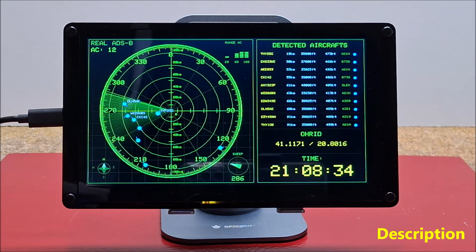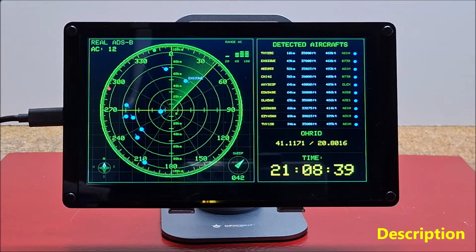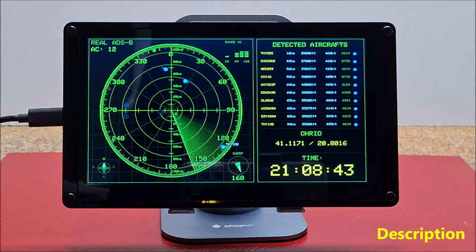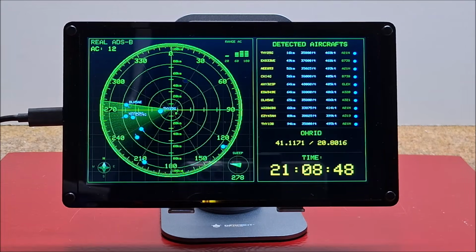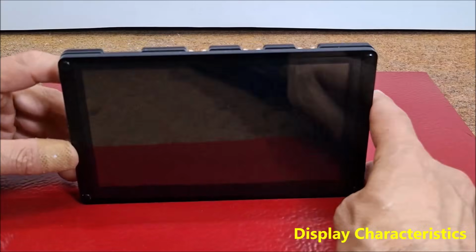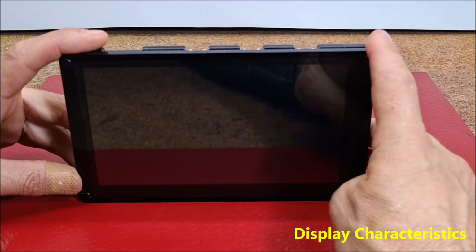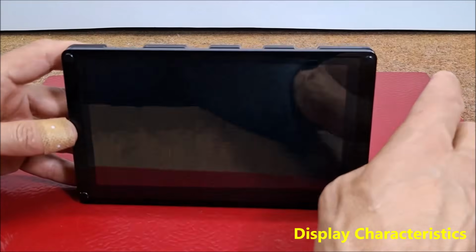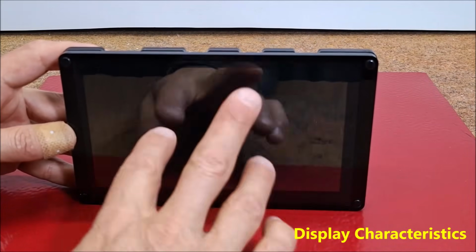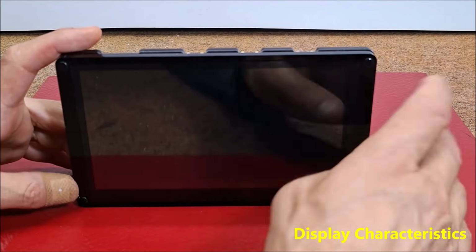A huge advantage in making this project is the fact that it uses the ESP32 S3 Crow Panel 7-inch HMI display, which means that there is no need for any soldering and making a corresponding box. Physically, the device is actually an Elecrow Crow Panel 7-inch HMI display, which costs around $30 along with the acrylic case. It consists of a 7-inch LCD display with capacitive touch, and an ESP32 S3 microcontroller that controls the display.